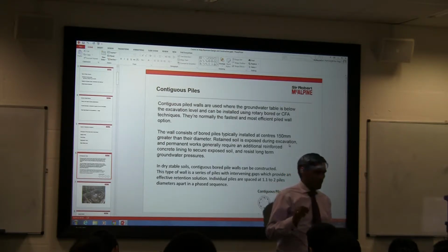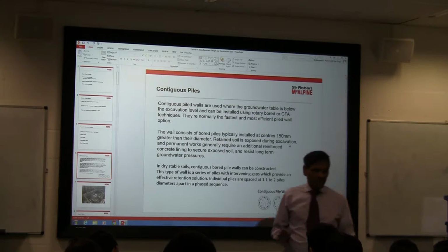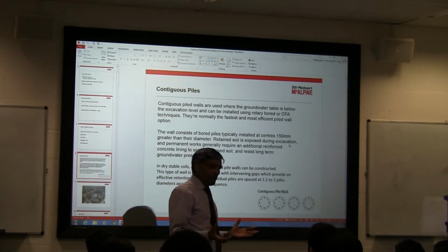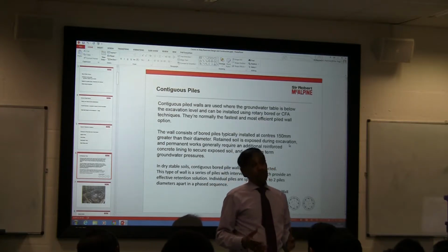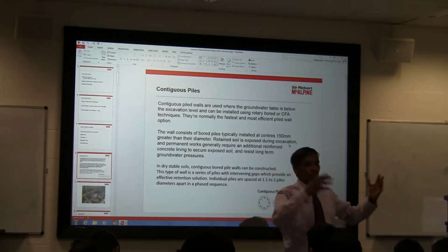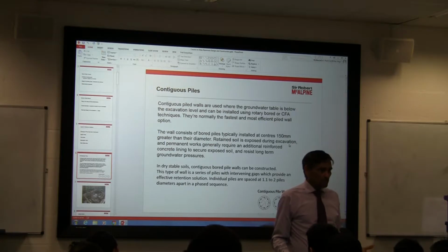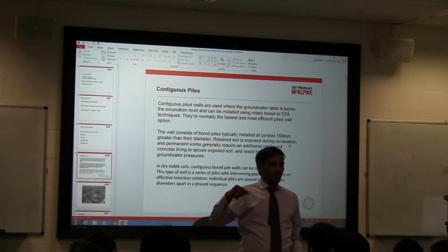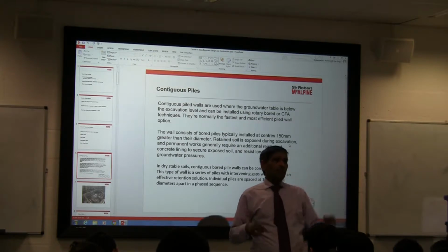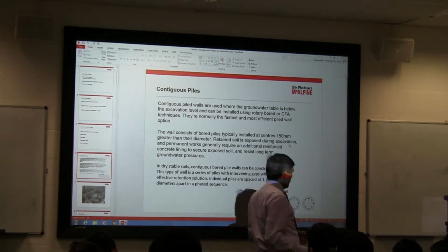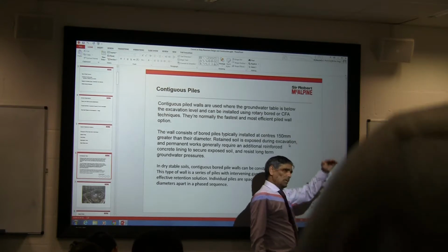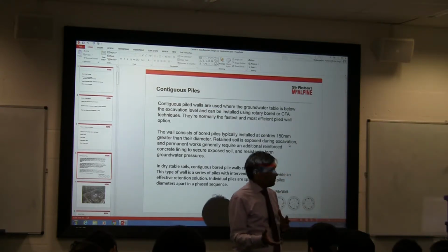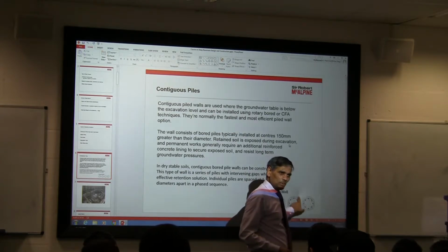So you've got to make sure it is absolutely dry, and if you find it, we do find sometimes, there are perched water tables which we can never estimate. We talk about a large size, let us say 50 meters by 50 meters, 10 times the size of this room. Yes? So what happens is, we don't know where the perched water table could be, in one corner. Yeah? So if we get into that sort of problem, we try to go down to a lower level and we plug the water. Sometimes it could be an issue, sometimes it could not be, it depends on how much water is coming through there.